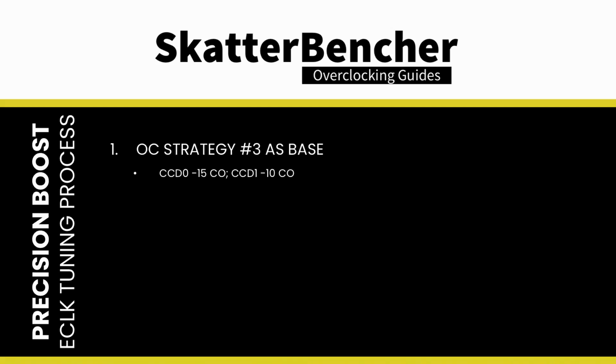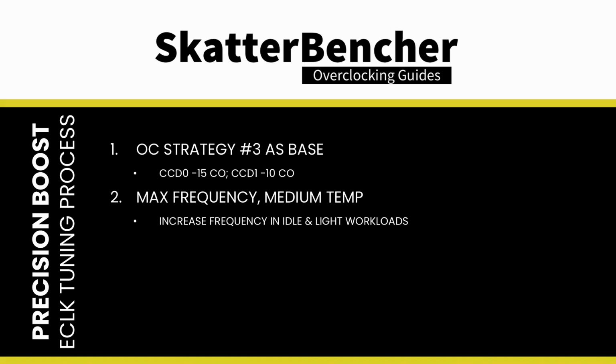So as the basis for this overclocking strategy, I rely on the settings from OC strategy number 3 with Curve Optimizer set to -15 for CCD0 and -10 for CCD1. Then I try setting the Curve Shaper for medium temperatures to -5, starting with maximum frequency. This setting further undervolts the CPU in idle and light load scenarios.